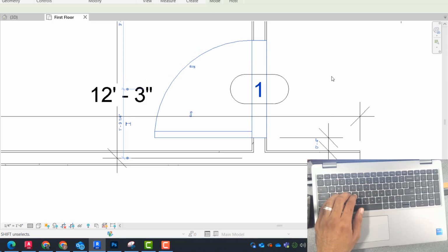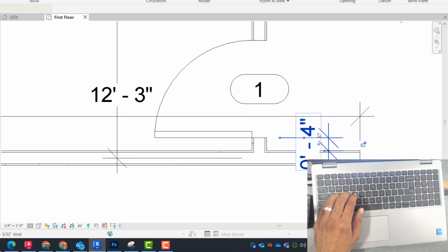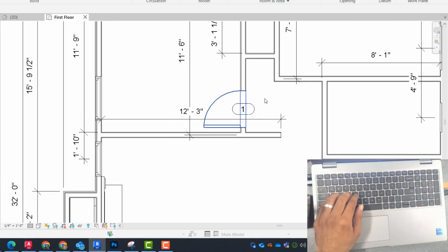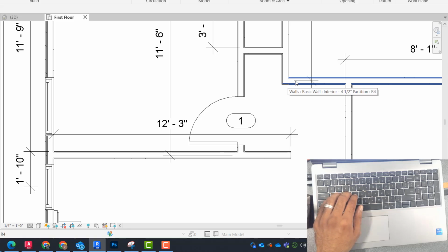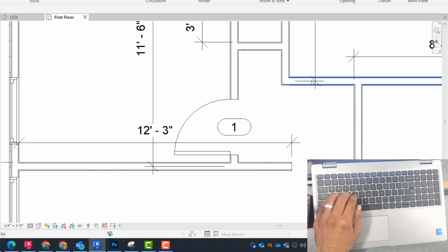I would specifically make it at least 3.5, 4 inches, because you're going to have a jack stud and a king stud that would frame that opening. So I'm going to go ahead and delete my 4-inch here after I place my door there, and we can specify this. And then the same door would go on this wall.